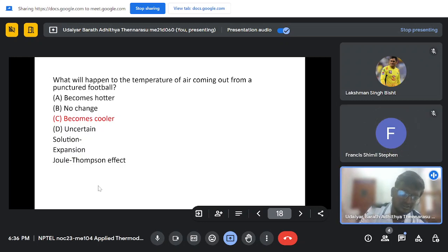You can do a velocity balance as well, but in this case most of the energy is consumed by the gas itself to reduce the pressure. In the nozzle, the pressure drop is converted to velocity, but here the gas itself consumes that energy for the expansion process. During expansion your volume is expanding, which means it needs some energy to expand, so the density of the fluid will go down.